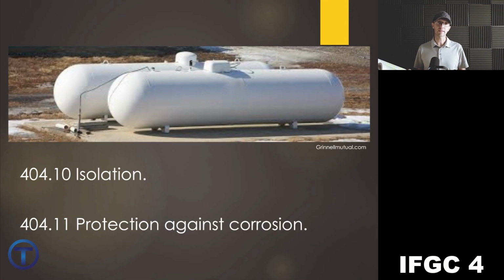404.10 talks about isolation. This is dealing with transferring gas from an LP storage tank into the building. We might be using dissimilar metals. Say we're using copper here and then steel there. We have to make sure that those are isolated with the proper dielectric unions.